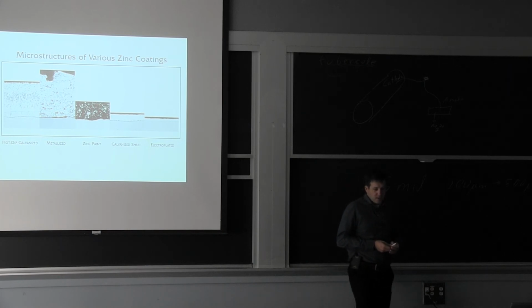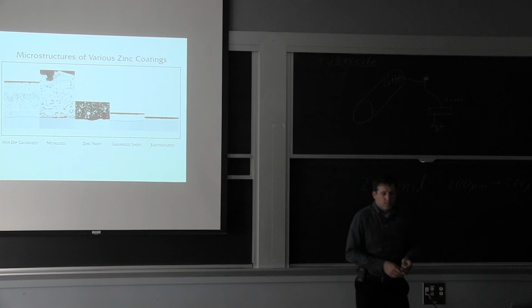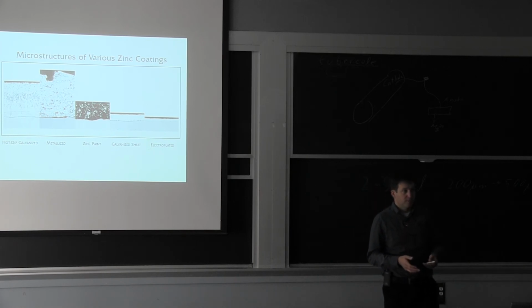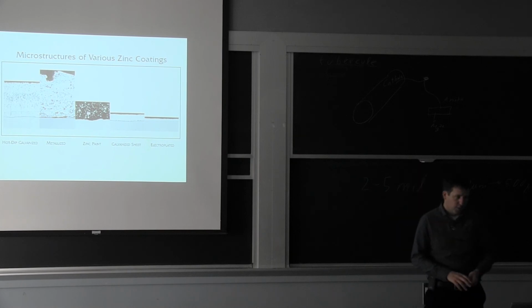If you have cyclic loading, and that's the next topic we're going to cover, like turbine components, you do need to worry about that mechanical compatibility, which is what you're referring to. If you're going to have high loads, you're thinking about the galvanizing not holding up, right? Yeah, it's true. It won't. You can actually create cracks through it, and they're going to continue through the base metal. So for higher load applications, you're starting to think about more expensive coatings, and these can be metallic coatings, and you can spray them, and we'll cover that.